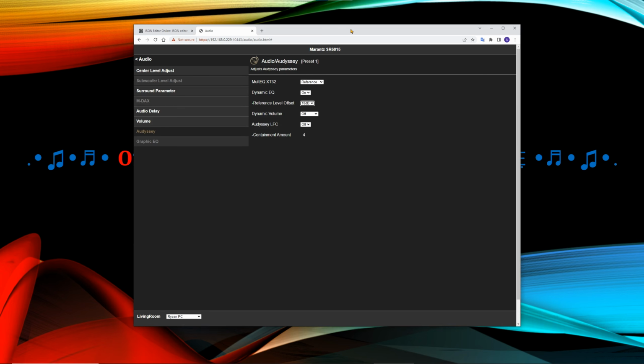You have to set the volume level to the maximum level you listen to your system, because we will tune the system, including surround speakers, to give the perfect target response at that level with Dynamic EQ on. For levels below that, the EQ will correctly apply some boost to bass and high frequency, replicating the so-called EQ loudness contours, and you will be able to adjust the strength of that to your taste by changing the reference level offset here, because from 10 dB you can go up or down to 5 or 15. That is the reason I picked 10 dB.